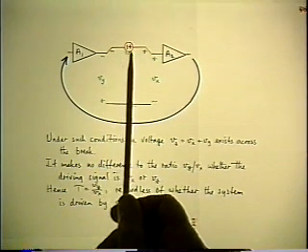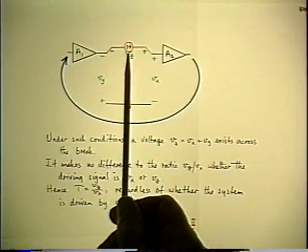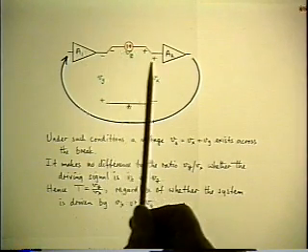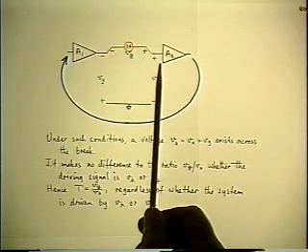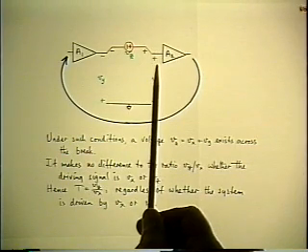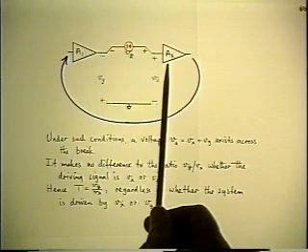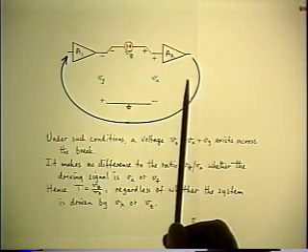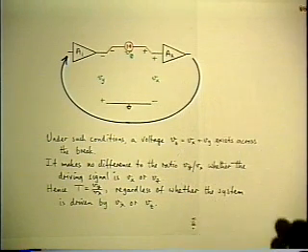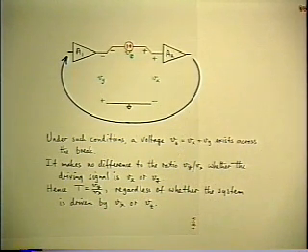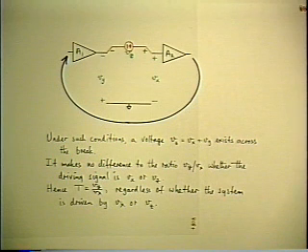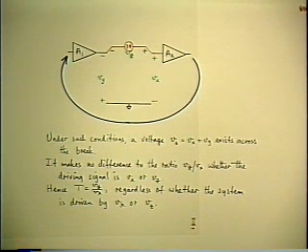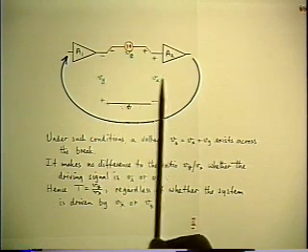This is an ideal voltage source, zero impedance. The loop remains closed. The circuit topology is exactly the same. The DC connection exists. The loop is self-stabilized. The operating points stay exactly the same, automatically. And you still measure the required ratio.